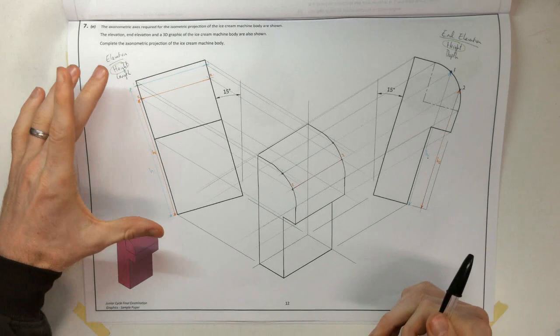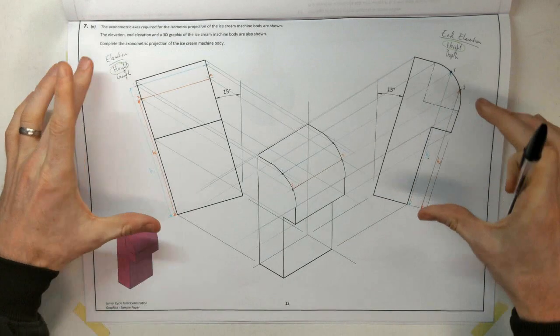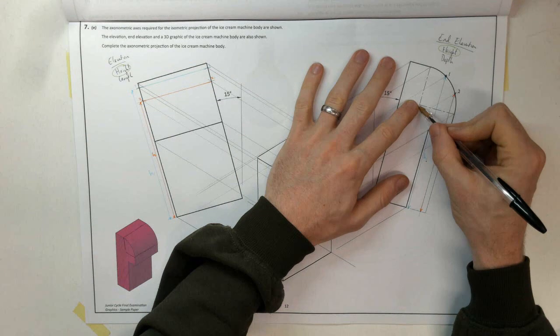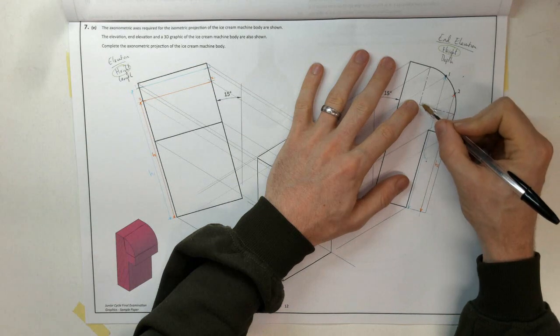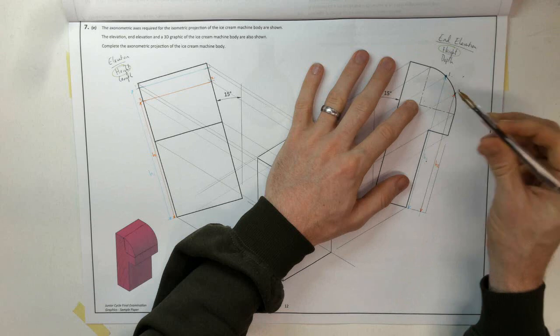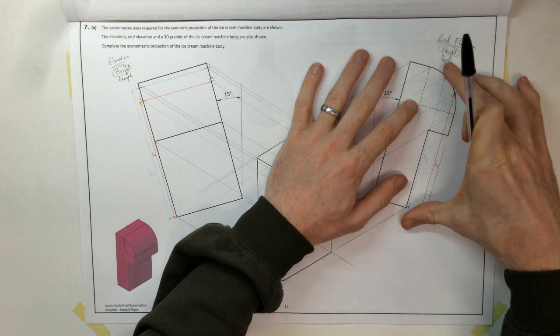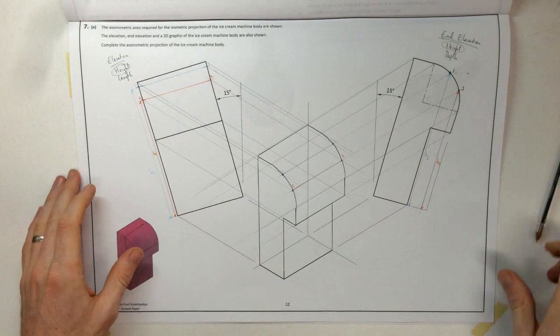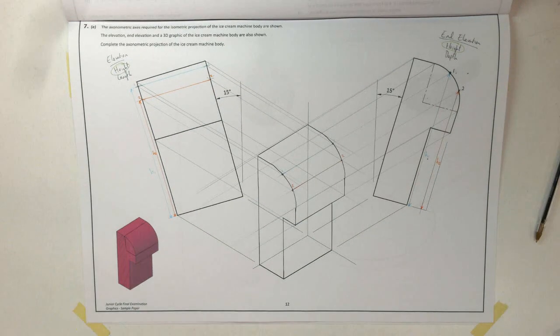Like I said, identifying heights between views, that is the important part. If you wanted to find any other point, if you even divided up 60, 30, maybe that's what you do in class, that's fine, but the key thing is establishing a height and finding the corresponding height over here to locate the points. So that's question 7 complete.